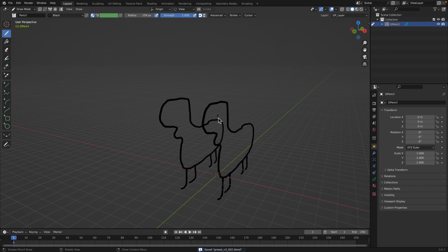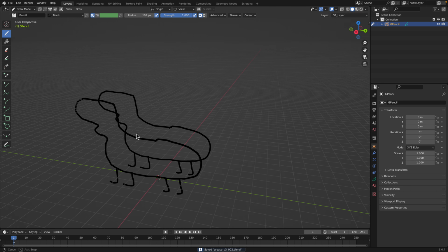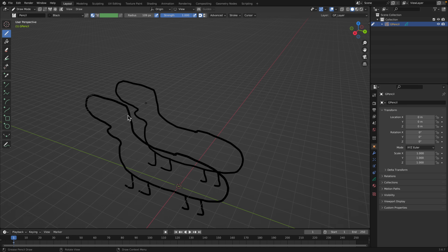In this case, we have these shapes, these dinosaurs with 4 legs, and we can connect the dots, right? Okay, you probably didn't know, you can connect the dots by using strokes. So stroke placement is going to be stroke, and we're going to use, instead of all points, we're going to use the end points or just the first point. Snap only to, I think the end points, the most useful.